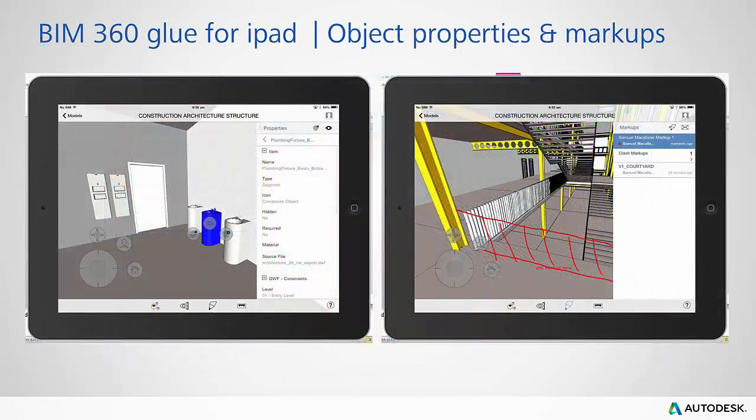Also, the data transfers onto the iPad. So you can see here we can read BIM authoring data even in the iPad environment. So if we're looking at that particular component in the bathroom, or if there are missing parts of the model or there are changes on site, we can do field markups with the pen tool and then email team members.